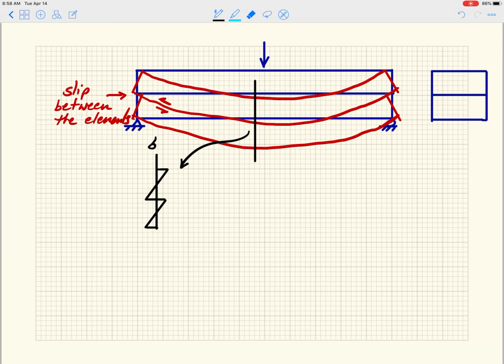So the moment of inertia of this cross section here, I'll do it in blue. I total equals I1 plus I2, right? So if this guy is I1, and this guy is I2, they do not have an AD squared term because they each have their own neutral axes, right? So they're bending separate from one another. This is what we refer to as non-composite.